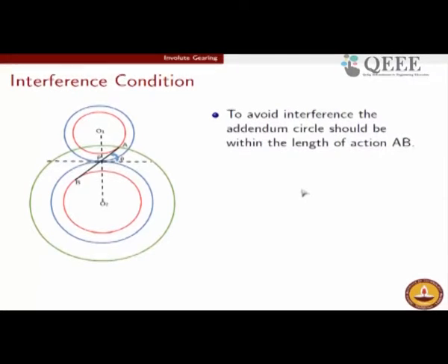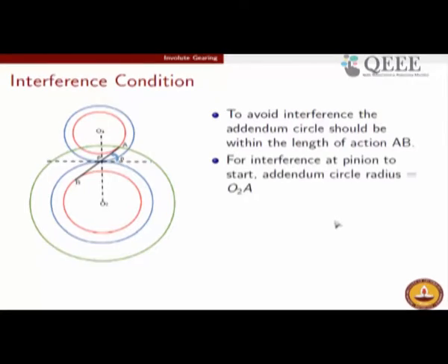In the region between the base circle and the dedendum circle, this will be denied. So we have to ensure that the contact never takes place in that region. If that can be ensured, then we will avoid this perplexing condition of interference. We will analyze what that condition boils down to.